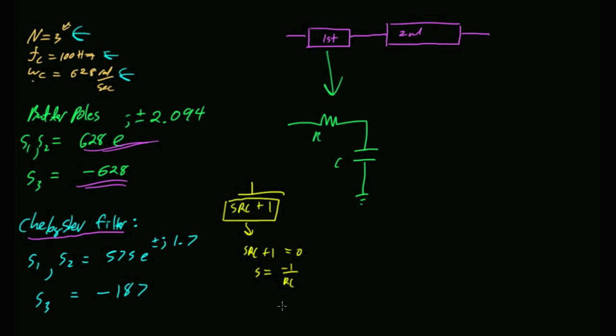Where do I want, what's the actual number where I want my pole to go? That frequency, negative 187. Why? Because I'm trying to pick off a single pole, a single real pole to build my Chebyshev filter.